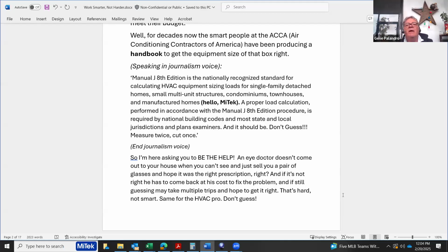Hello, Mytech. A proper load calculation performed in accordance with the Manual J 8th edition procedure is required by national building codes and most state and local jurisdictions and plans examiners. And if it's not, it will be soon. You don't want to get a call or talk to a Mr. Plans Examiner without a Manual J load calculation. And it should be. Don't guess. Measure twice, cut once. One of my many keywords you'll hear throughout this discussion.